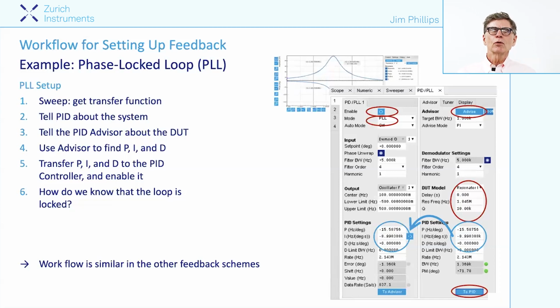You can also test its step response by adjusting the set point abruptly. And that allows you to adjust the coefficients in this PID controller to optimize the step response to get it to be as quick as possible, but without overshoot or ringing. And you can fully adjust the loop. So with that, I'll ask Kıvanç to show us some examples.